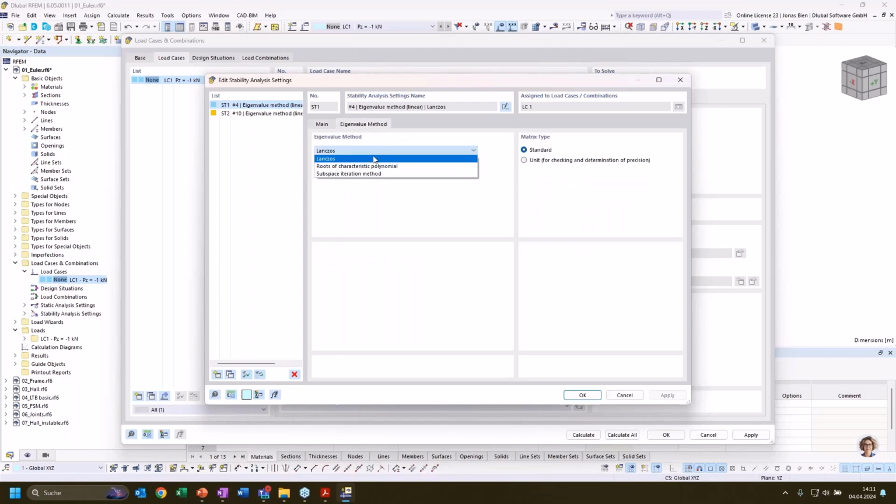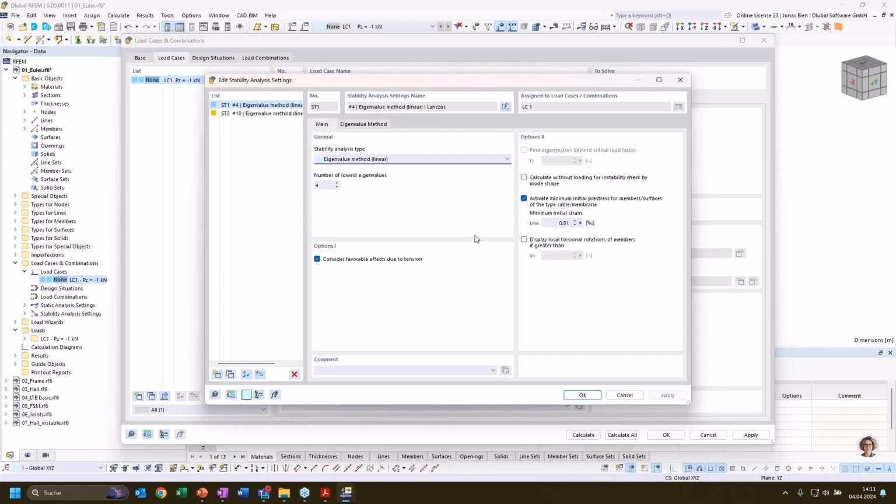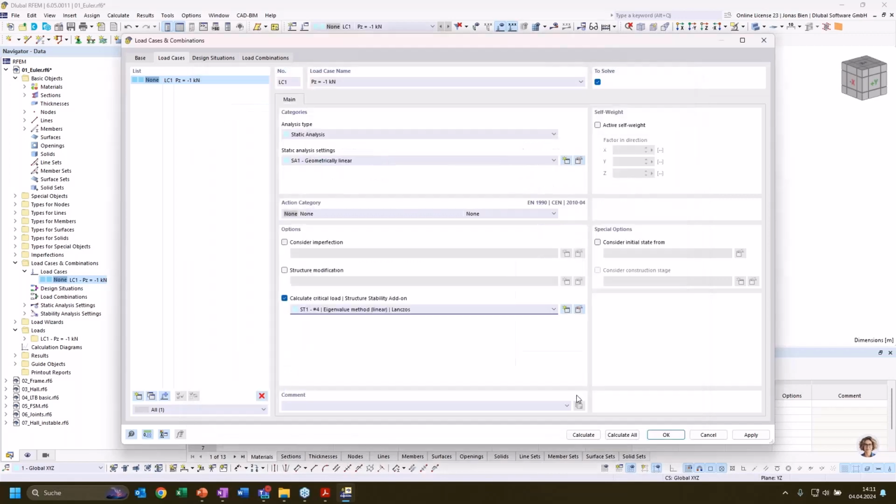And then we have these multiple solver variants to solve the determinant of our eigenvalue problem. But the default solver should mostly suit us for this problem. There might be cases where you have subsystems that are not connected to each other. Then this default solver will throw an error and suggest another solver variant.